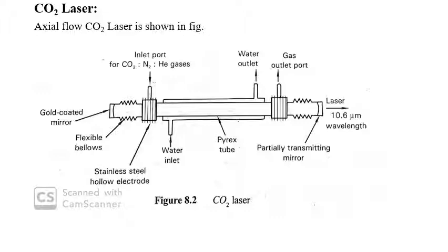Due to its high power efficiency, CO2 laser is used for cutting thick metals and also in the welding process. In a CO2 laser, a mixture of CO2 carbon dioxide, N2 nitrogen and He helium is continuously circulated through a gas tube so as to minimize consumption of gases.